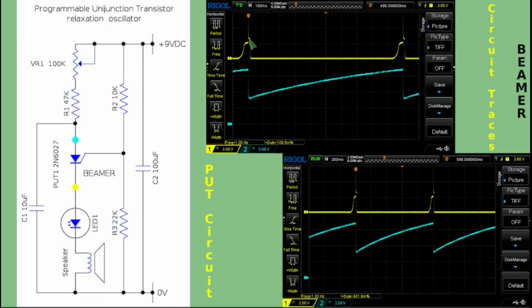I could calculate the power of this, but it is limited by, of course, the impedances of the various components in the line, including the resistance within the capacitor itself. But you're quite welcome to do, what is it, half CV squared or Q equals CV, Q equals IT, and can calculate this. But the number is actually quite large in terms of current. But bear in mind that it is limited by the intrinsic, appropriate word for this device, intrinsic resistance values in this path. I thought I would just add that this is the way I think of this rather interesting little near obsolete device, is that when it triggers, just kind of mentally think that all these 3 terminals join together in a short circuit, and that discharges that capacitor into the load.